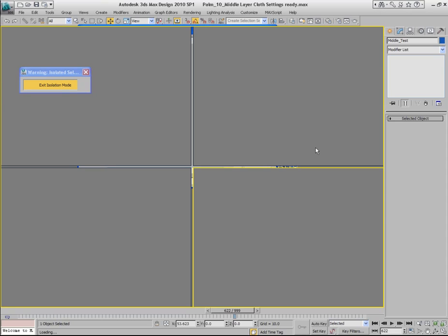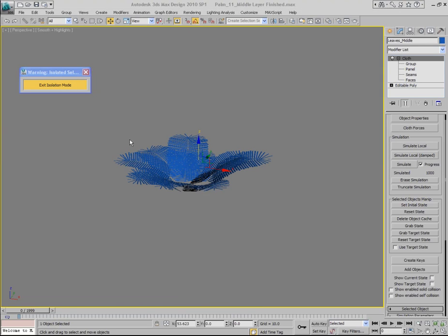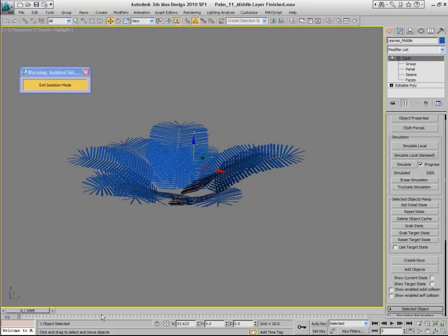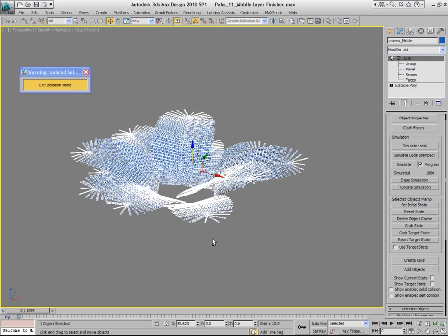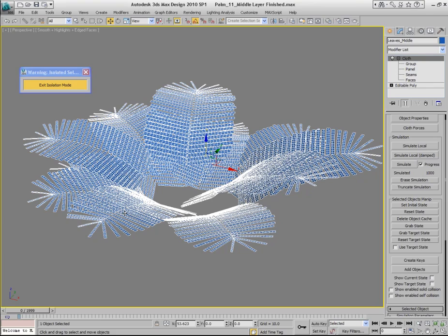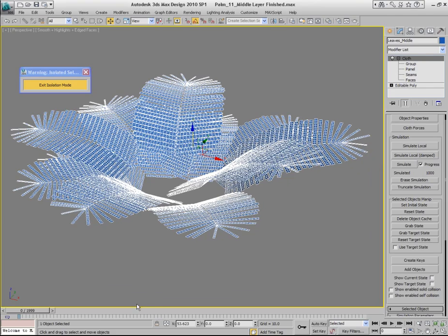Let's give it 15 seconds or so to load. Okay, the reason why these files took that long to load is because when you run the simulation by clicking the simulate button and calculating the simulation for every individual frame, this information is then stored within the max file that you save. And apparently it uses some hard drive space, because it is essentially remembering every individual vertex position of the subject for every frame.